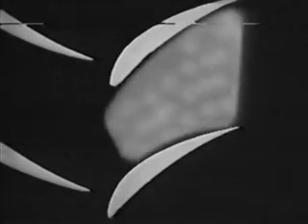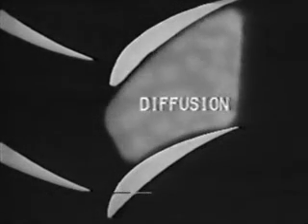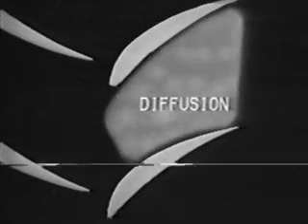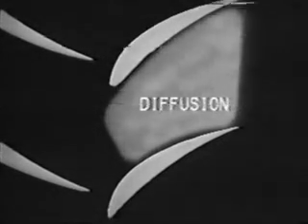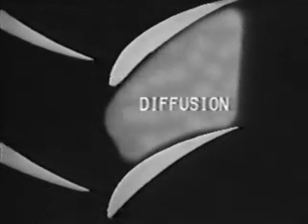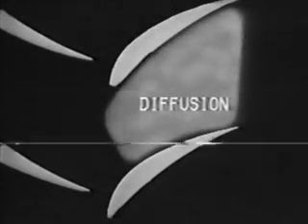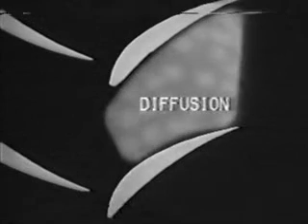It's at this point, in the spaces between stator blades, where air is slowed down and we gain air pressure. This is called diffusion, and it is the key principle which makes the compressor work. The space between rotor blades acts as a diffuser too, slowing the air velocity.